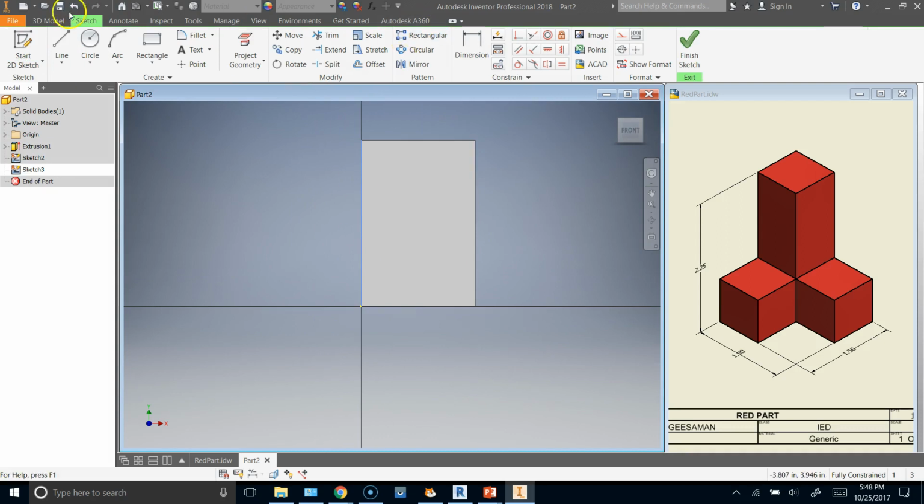On that face, I'm going to draw the rectangle I was talking about. So I'm going to get rid of a rectangle by attaching to the upper right corner, and then coming down about 1.5 inches down for 2 blocks and about 3/4 of an inch over for 1 block. And I'm going to put in some dimensional constraints now. This here is 1.5 inches for 2 blocks high. This here is 0.75 inches for 1 block over. Purple, fully constrained, I'm good.